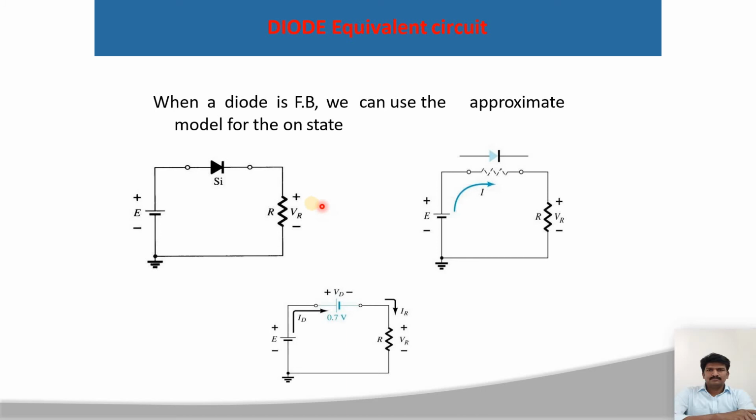In between that one we have the R. You can call it a load resistor here. Here this one is representing the diode with the resistance. Here resistance may be infinite in the reverse bias, and resistance will become 0 in the forward bias. That is the representation. We have the VR as a load resistor. Here we have the voltage, whatever you applied here, it is having ground. Okay, the current is going to be passing like this.